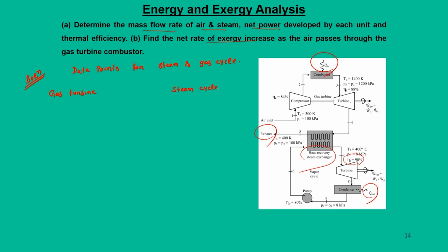What data we normally require are the enthalpy points and entropy points. So, we say state, and enthalpy in kilojoule per kg, and entropy, here we need to know absolute entropy, that is kilojoule per kg Kelvin, and this absolute entropy is a function of temperature that we can obtain from any thermodynamics book for air.